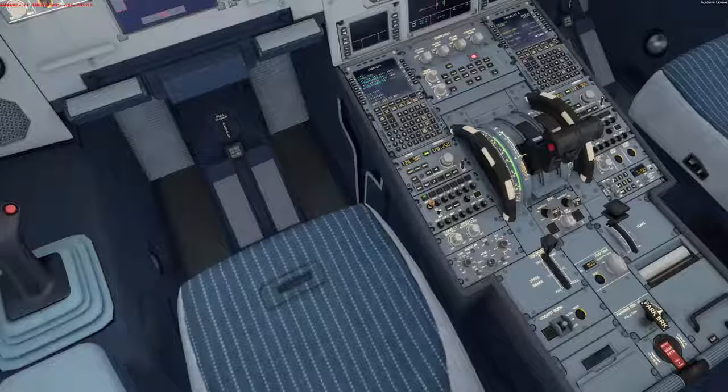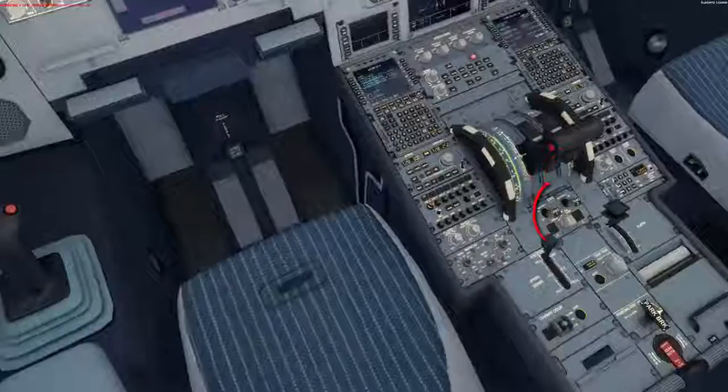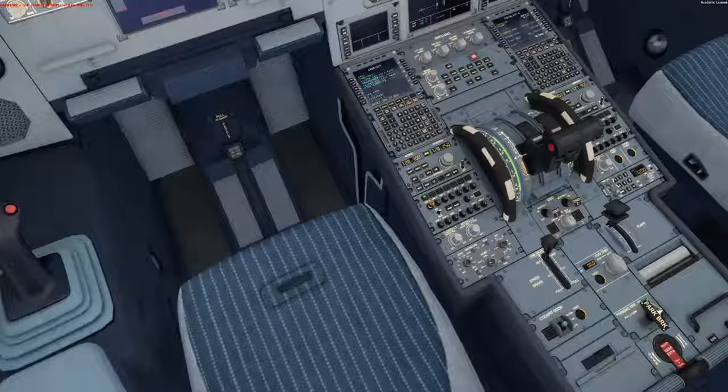Batteries, both on. Electrical power, external power is on. Navigation lights, on. Engines master, both off. Engine mode selector, checked, normal. Landing gear lever, checked. Parking brake, on. Flaps, checked, position. Speed brake lever, checked, retracted. Thrust levers, idle. Transponder mode, checked, standby. Radio control panel, on. ECAM recall. And I haven't pressed the ECAM recall button now, so if I do it now, checked. Anti-skid, on.